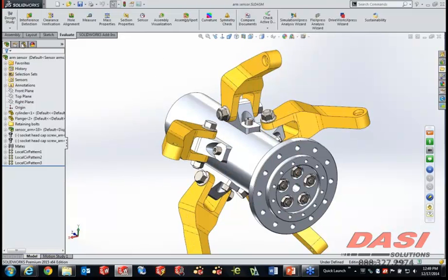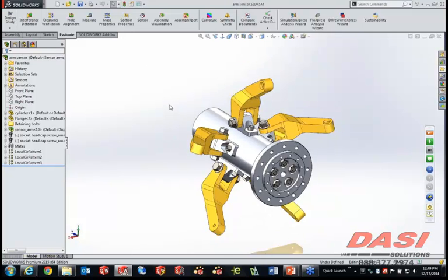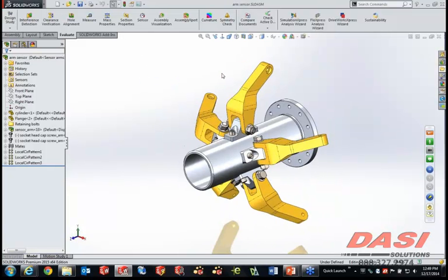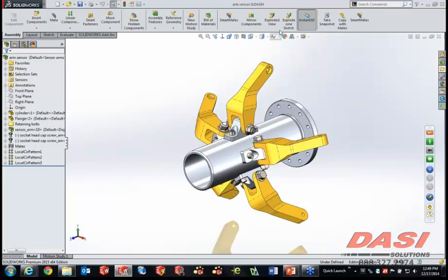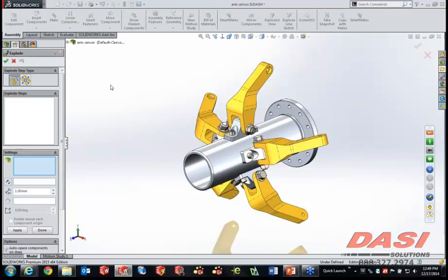Now sectioning is one of the things I wanted to show, but the other is exploded views. With this assembly, I want to take everything that we've got here, and we're just going to run a brand new exploded view. For the entire history of SolidWorks, and really most CAD systems, exploded views have always been linear transitions, translate apart from one direction to another.